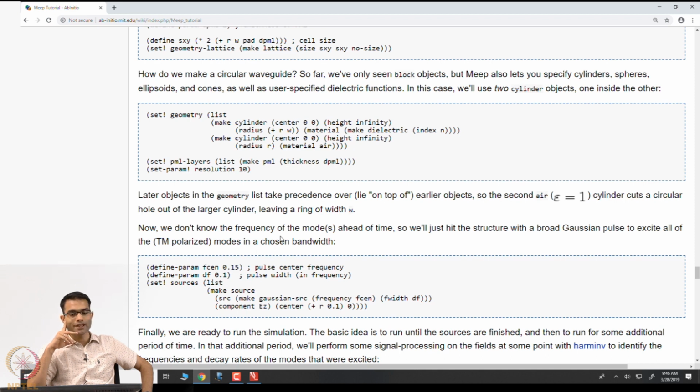I can, in FDTD, specify a source. Well, okay, after that what? Supposing my task is, someone gives me a structure and says find out the resonant frequencies of the structure. Excite it with all frequencies, right? All frequencies is technically impossible, so wideband, right? So, step 1 is excite it with a wideband.